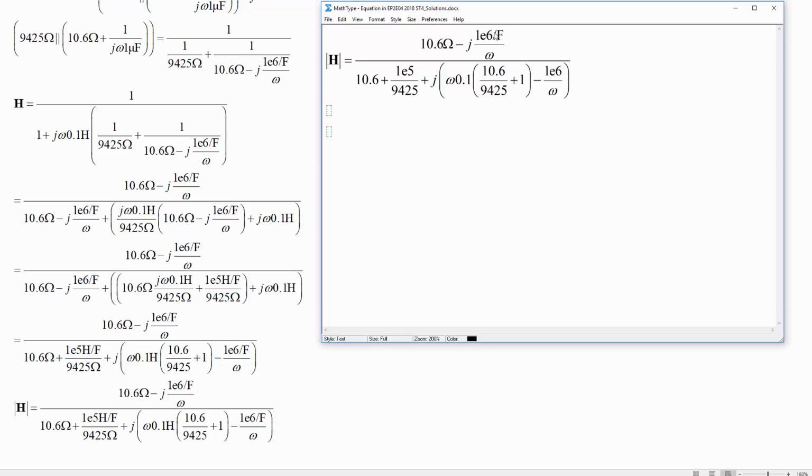If we take this whole thing and divide it by the ohms that we've got here, so we want to take that out of everything, that means we end up dividing by ohms here, which is going to be seconds. And same thing, this was henries, we're dividing by ohms, so that means seconds. And this was a 1 over farad. If we have another ohms that we end up with multiplied by that, then we get seconds. So everything is all good. We've got all the omegas multiplied by seconds to cancel out the units.